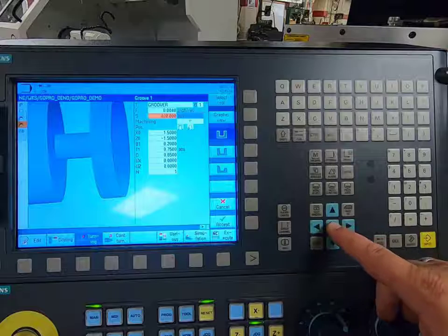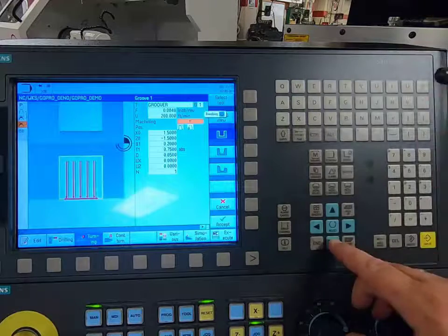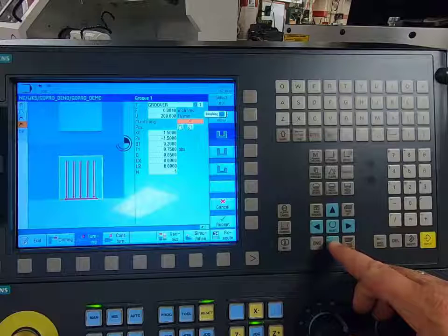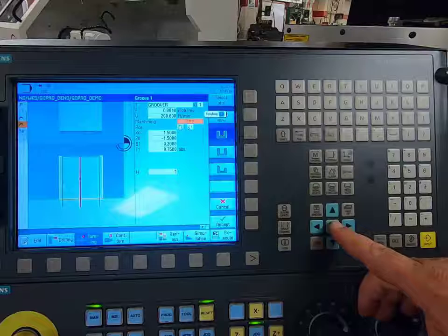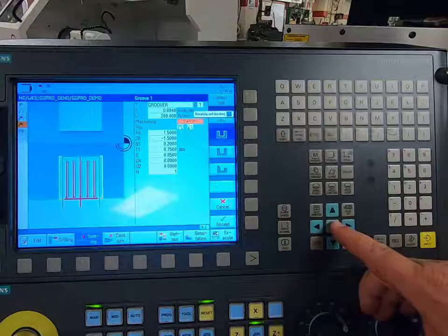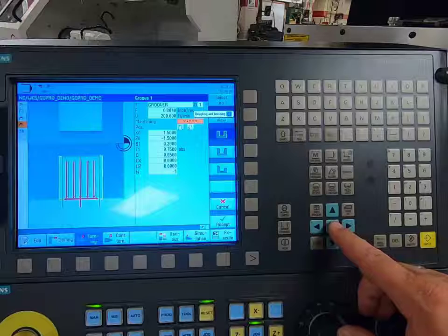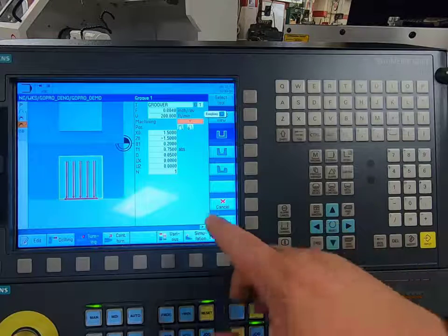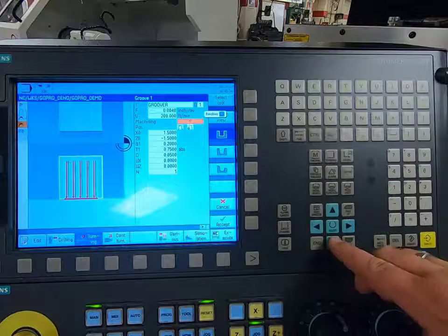It does not translate over. So that way, if you want to keep it at that same RPM, you won't be affecting it unless you physically change it. Okay, so I am doing a roughing. I'm not doing a finishing. A finishing would just come right in there. I can do a roughing and a finishing, or I can just do my roughing, and then right here on this UX and UZ where I leave excess material, I'm just not going to do that.